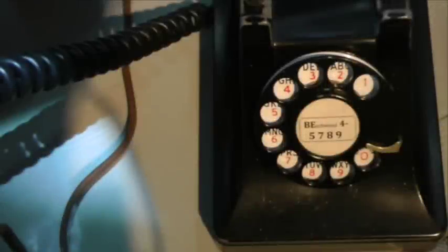A small portion of the ringing current is passed through a 0.04 microfarad capacitor onto the incoming ring lead. This current passes through the calling telephone, where it generates an audible tone through the receiver. This tone provides an indication to the calling station that the called station is ringing. It sounds like this.